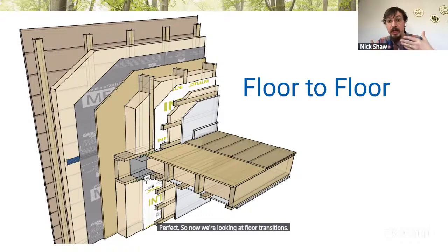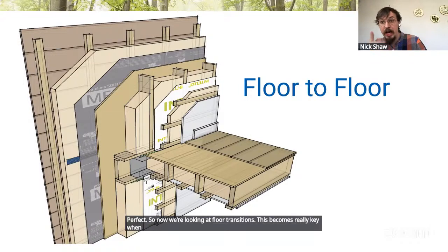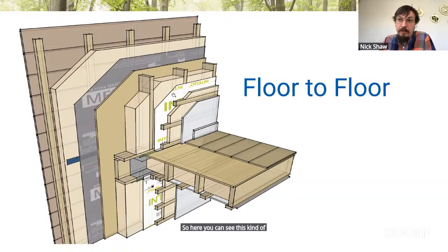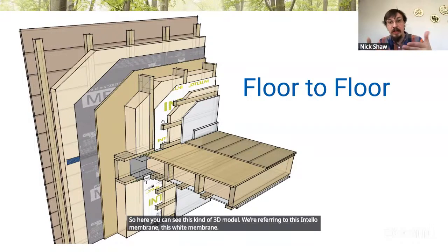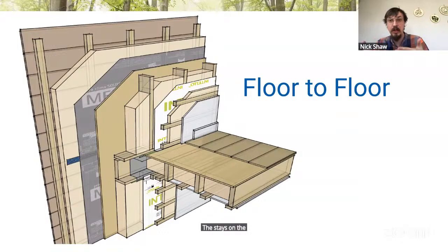So now we're looking at floor transitions. This becomes really key when we have an interior air barrier, the Intello Plus membrane. So here you can see this 3D model. We're referring to this Intello membrane, this white membrane, that stays on the interior side of your installation.